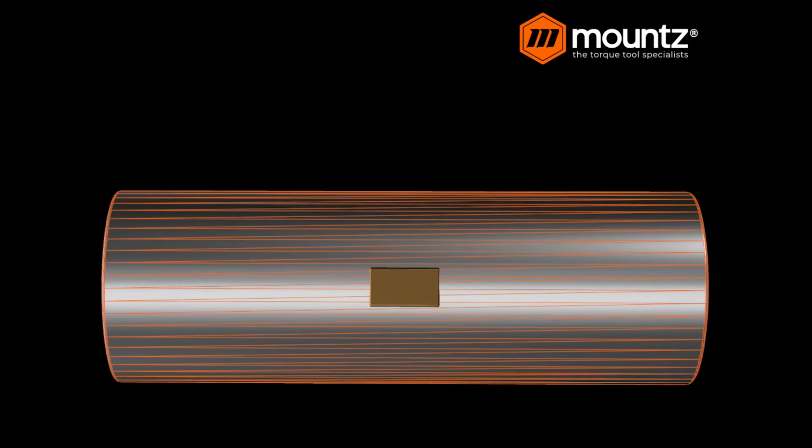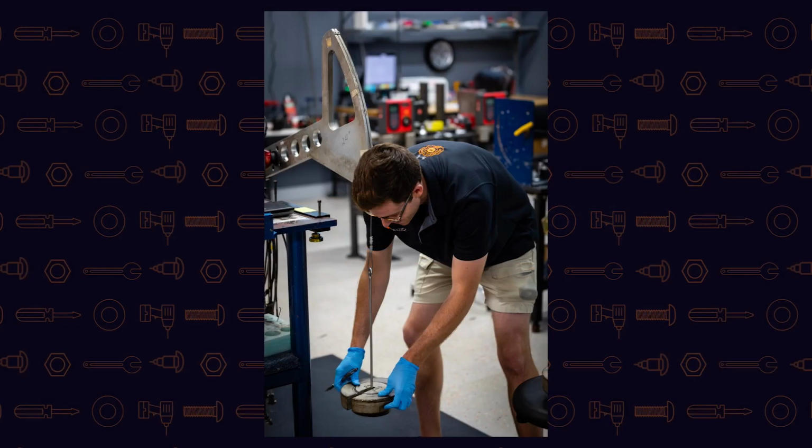And so we use the torque analyzer and the strain gauge to give us a signal of the amount of torque that was generated when that torsion happens. And that is all culminated during the actual calibration of the torque sensor or the strain gauge with the use of dead weights. We have our force, which is our weights, out at a certain distance.